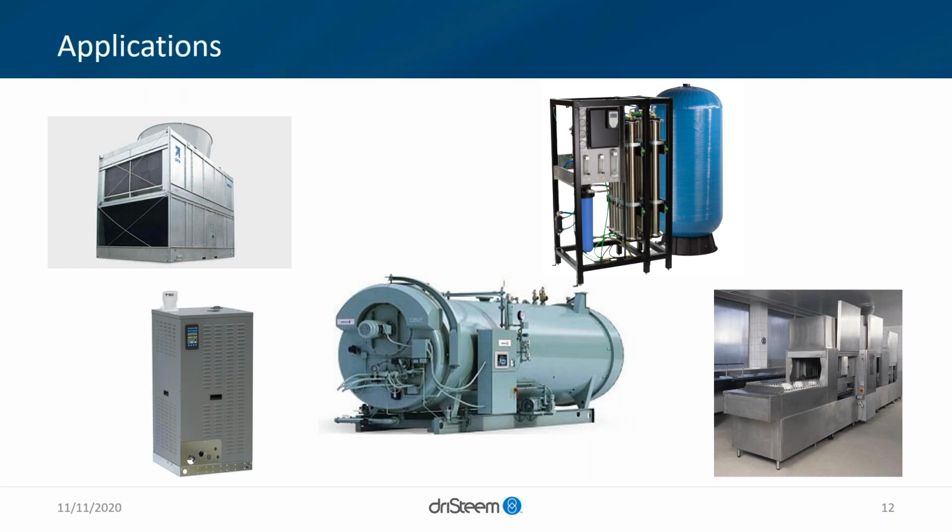So for example, the top left picture is a cooling tower, where you see that bracing on the bottom left of that. There's actually plastic fill that is the heat exchange surface for the evaporation to occur. If you see that completely white, you probably had scale occur on that system. So one thing you can do along with chemical treatment is soften that system.